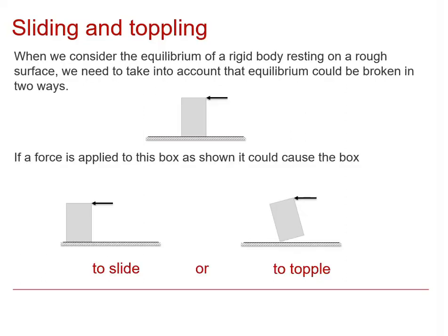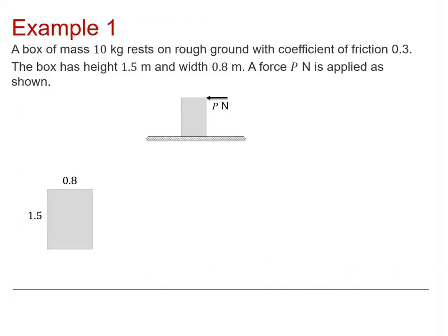Now let me take you back for a moment to the previous slide. When you're in the position of toppling, if you think about the force diagram, the normal reaction force has to operate through that corner, and then it will be at right angles to the plane. Clearly it would operate upwards. That's important because we want to consider it just before it topples, which will be when the normal reaction force has just reached the corner.